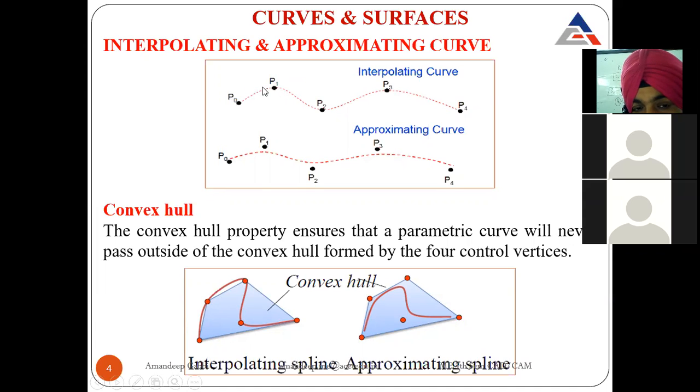That means the curve that is being generated is controlled by these points only. If you change the position, right? If you place your first dot here, second dot here, and instead of here, you place a dot slightly above that, the curve will reach from this end up to this. And if you place it downward, it will come here and end somewhere here. Wherever you place these points in AutoCAD, that curve will follow those points to form a particular curve.